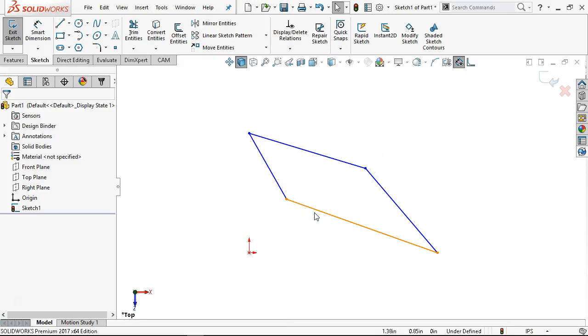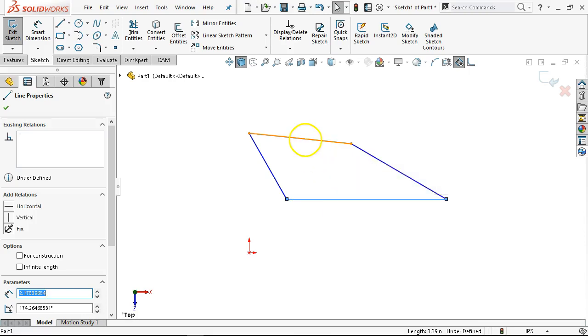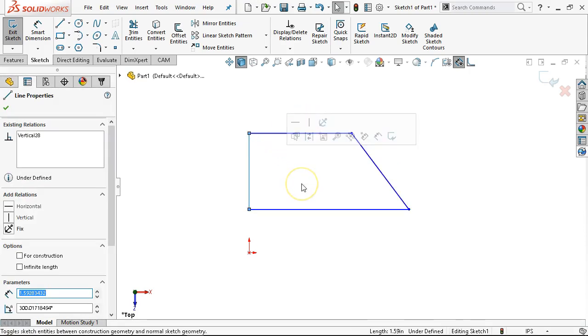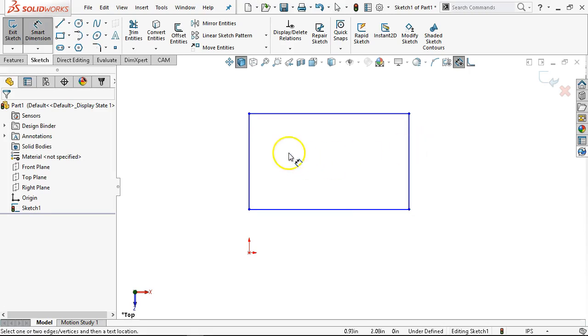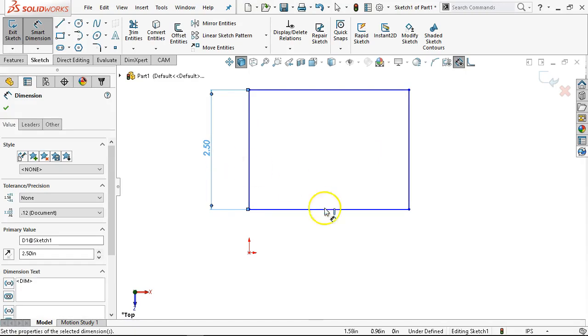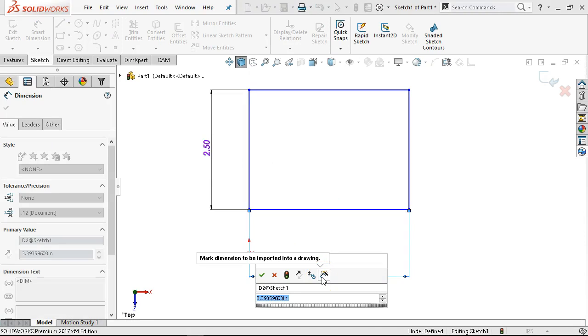So if I have to reconstruct this from scratch, what is going on in the background is, as we're generating those objects and it is inferring horizontal, it adds horizontal for me. It adds vertical. It's saving me in the process of sketching by paying attention to those little yellow boxes. It's doing this job for me. All right, so it doesn't take very long to reconstruct, but this is a rectangle. When we get into some of the chapter 2, chapter 3 sketches, this is the last thing I want to be doing.